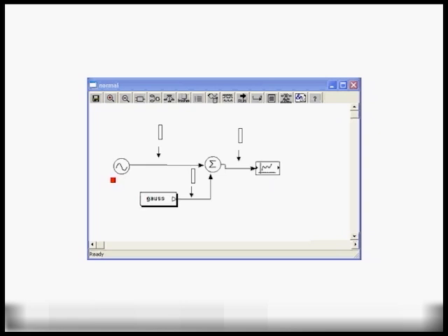One of the nice things about a Capsim simulation is that there is a very nice bounded size on the memory required in order to do a simulation. In this case, it's limited to 128 cells here, 128 cells on this buffer, and 128 cells on this buffer. Even though we can generate 10 million, 100 million samples, the actual memory used in Capsim is limited. This is a very important feature of Capsim. So you can actually simulate an unlimited number of samples, yet the memory footprint doesn't grow.